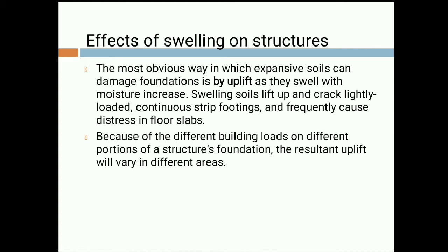Because of the different building loads on different portions of the structure's foundation, the resultant uplift will vary in different areas. Based on the contact area, the soil moisture variation around the structure will be different. That is, at the edges it will be different, at the center it will be different, and at the periphery of the building the amount of moisture will be different. Based on the availability of moisture content, there will be different expansion of the soil, which can result in differential settlement of a building.